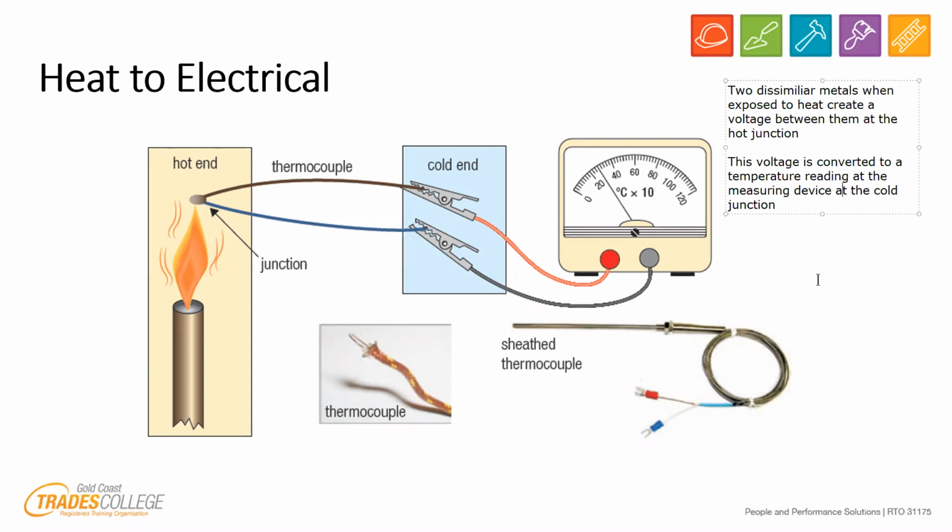Okay, so how does it do that? Basically, that will help you with your assessment, guys. So over here, we'll have something like, let's say these cables are designed to have a 0 to 10 volt reading. Well then that over here will be 0 to 10 volts.